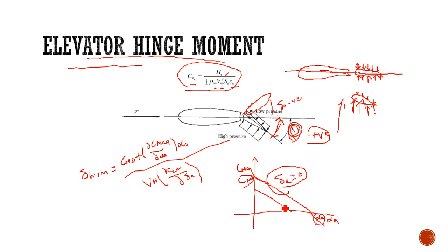So for that we will be getting a new trim angle of attack here, and the delta is also changed. When the deflection is changing, automatically the trim angle is also changing, and the moment is also changing here. Okay.